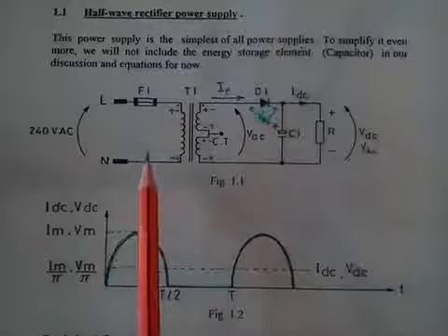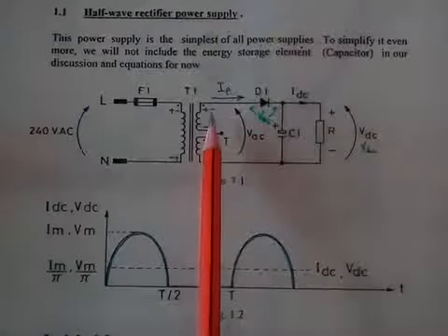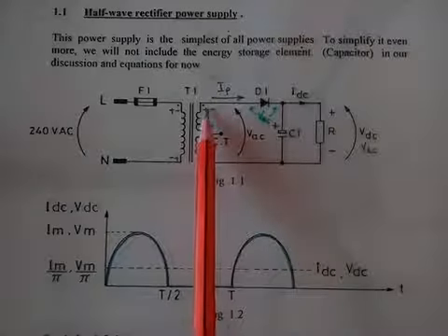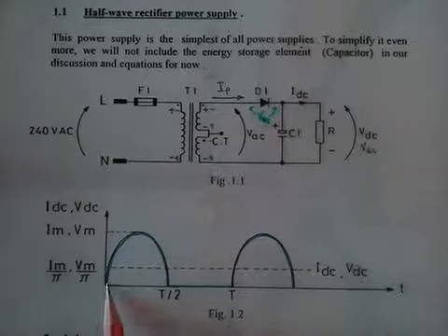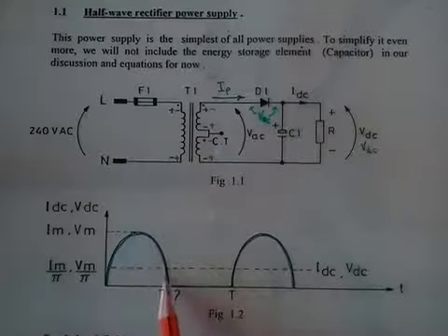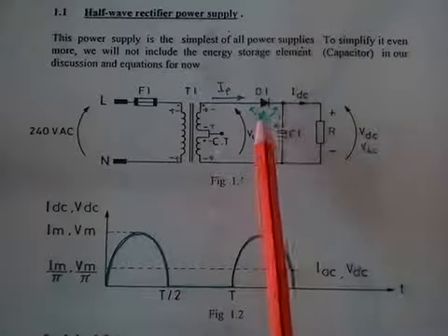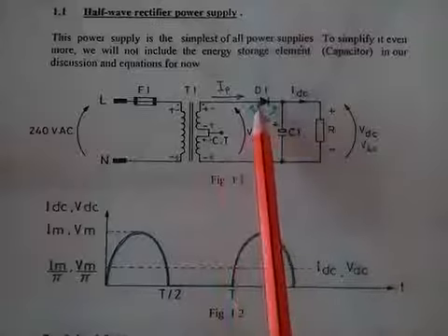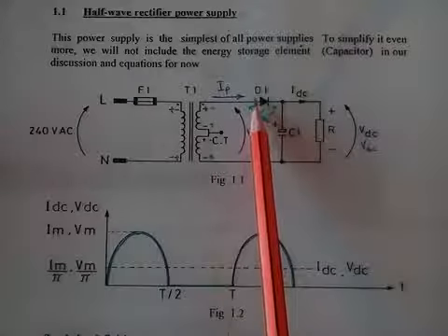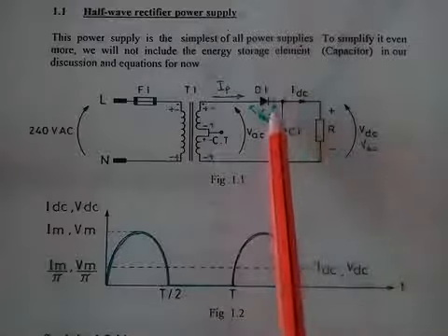Okay, going back to the function of the circuit, like we said before, when we have a positive here, a negative in here, and that's explained here in the half sine wave that you see in here. Okay, this diode will be forward biased because its anode has a positive and its cathode has a negative.